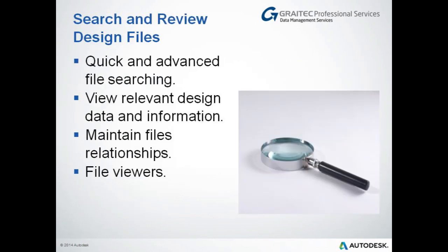You also have the ability to search your files, so you can quickly utilize advanced search functions that include searching inside the file. So there's functionality in there to do general quick searches on properties within files, but also the contents of those files. And on top of that, because of the way the Vault client works, which is the Explorer side of it that comes with Vault, you can start interrogating the data a little bit more to understand design changes, to understand what files are used where, getting preview information, and so on.